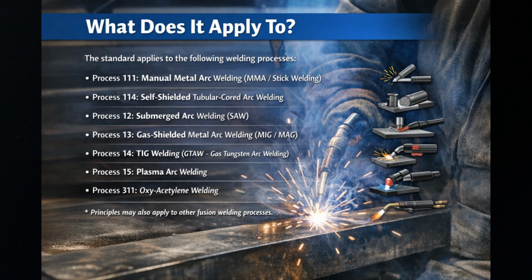The standard also notes that its principles may be applied to other fusion welding processes, even if those processes are not explicitly listed. Furthermore, a former process number, for example if a process was renumbered in a revision of ISO 4063, does not require a new qualification test.